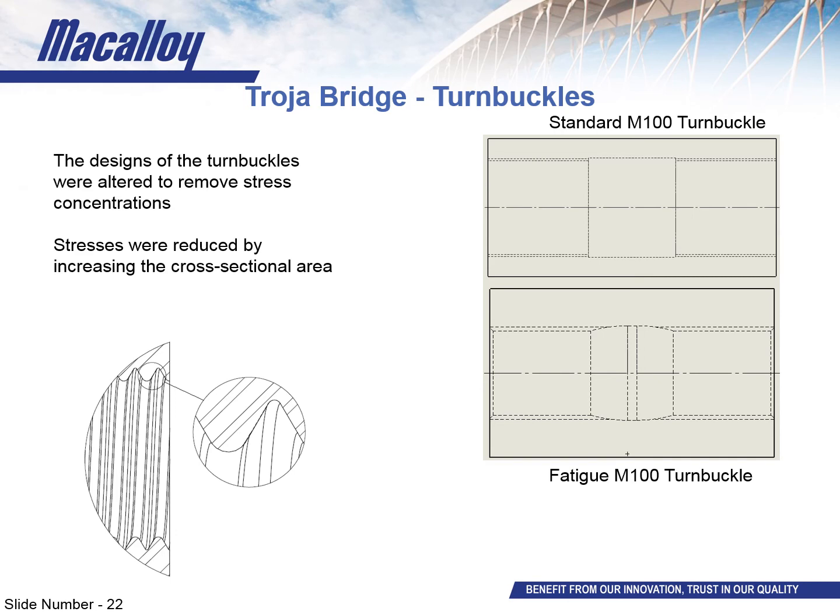Now you can probably notice this on the two diagrams with the difference in wall thickness. The material was also reviewed, so the material that was selected for the fatigue turnbuckle was softer and tougher than what's used for a standard turnbuckle. Now this lower hardness as well as increased toughness means that the chances of crack initiation and propagation reduce.